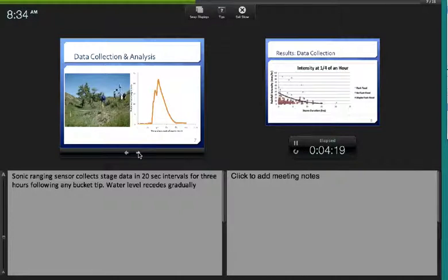And I'm going to point out this flash flood hydrograph, where it's water surface height versus time since the start of the storm. Flash floods are pretty easy to find in huge data sets because they are commonly characterized by this sharp ascension in water depth height. So this one reaches almost 25 centimeters. And then the water slowly recedes back to nothing. So that's a flash flood hydrograph that I found in the 6-year data.